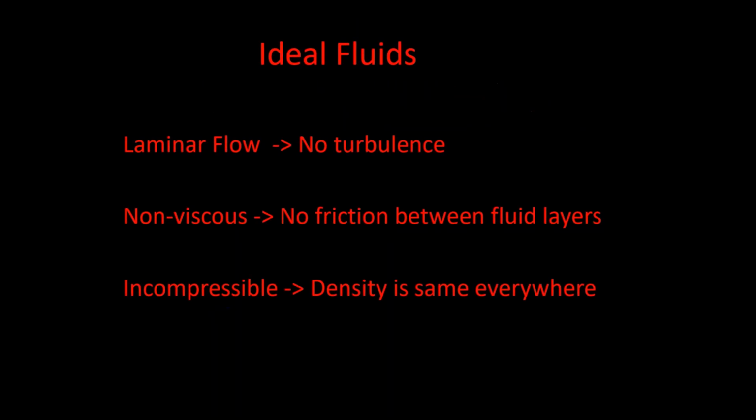So when we're looking at ideal fluids, which all of ours will be, laminar flow, as I said, over smooth objects and things like that, will be a case where you have no turbulence. Non-viscous fluids have no friction between the fluid layers, and if you assume your fluid is incompressible, it means its density is the same everywhere. All of the fluids that we're going to look at will abide by these terms, so we're not going to be too complicated in our mathematics.